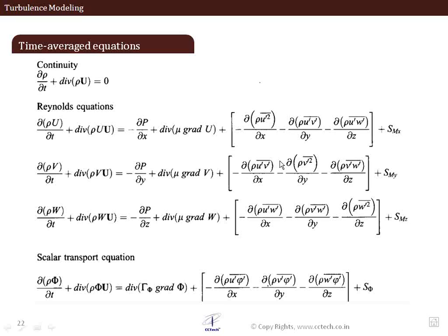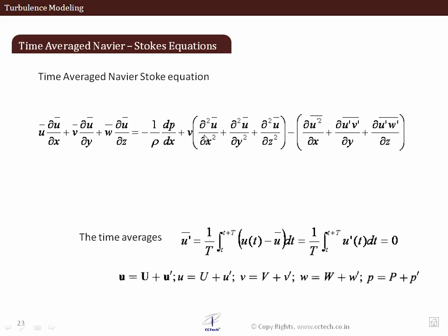Now if you remember, I said there are two approaches to the time averaging approach. One is to actually calculate these Reynolds stresses, and the other approach is to express them in terms of an eddy viscosity times the velocity gradient. So this is the eddy viscosity approach. We're going to have a look at these two approaches.